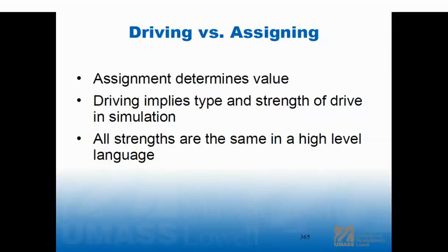In FPGA design, you really are just simulating the chip, and you don't worry as much about pads. There are special pads in FPGAs, but I do both, right? And I never really worried about pads in an FPGA except for maybe some special cases. And I always worry about it. I always see those two structures in ASIC design.